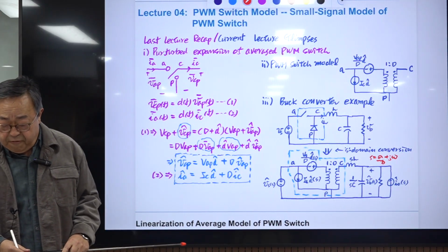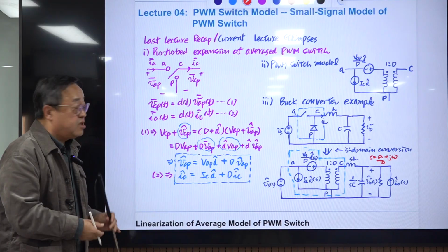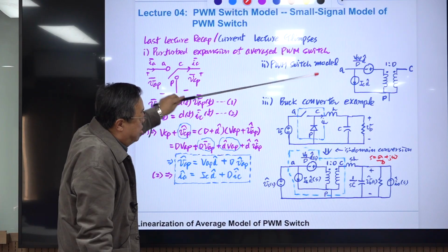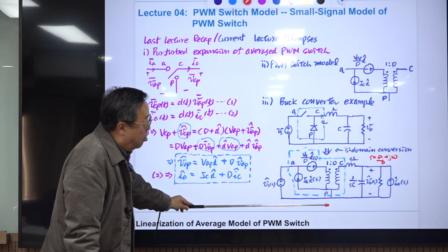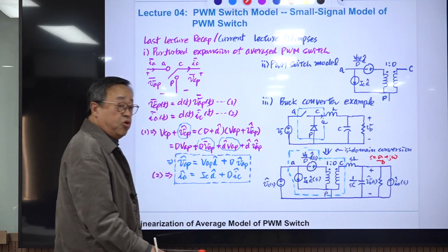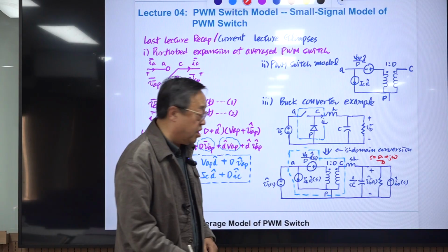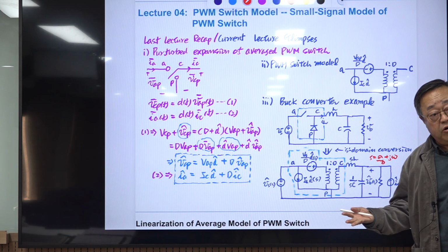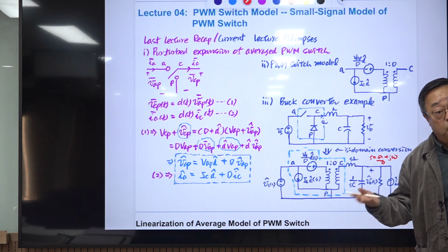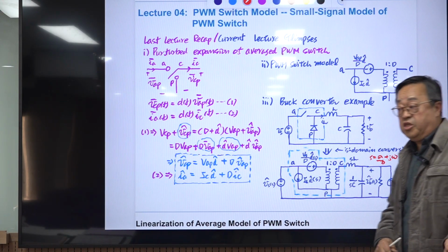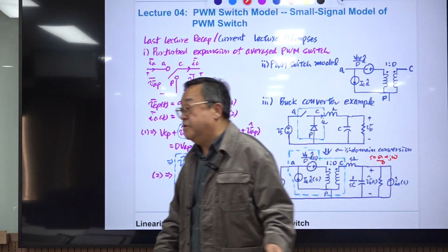The next slide starts with the derivation of this, and we'll discuss the generality of this model and its extension to other converters. We evaluate the validity and accuracy of this model using a computational method with some software, comparing the Bode plot of the transfer function of this converter with this small signal model, which is linear time invariant.